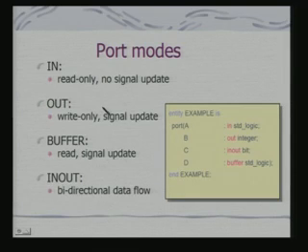Then, in the black box, we have used port. Ports can be in, out, buffer, inout. If it is an in port, there is no signal update; out is write only, so there has to be a signal update.